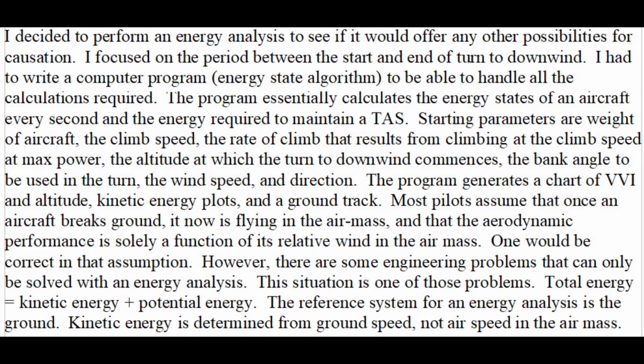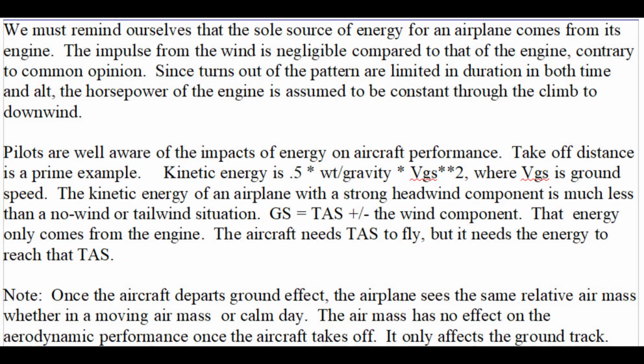Total energy equals kinetic energy plus potential energy. The reference system for an energy analysis is the ground. Kinetic energy is determined from ground speed, not airspeed in the air mass. We must remind ourselves that the sole source of energy for an airplane comes from its engine. The impulse from the wind is negligible compared to that of the engine, contrary to common opinion.